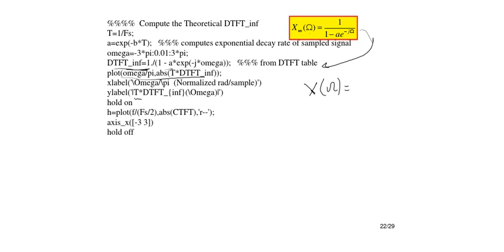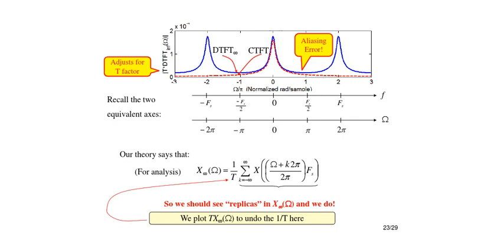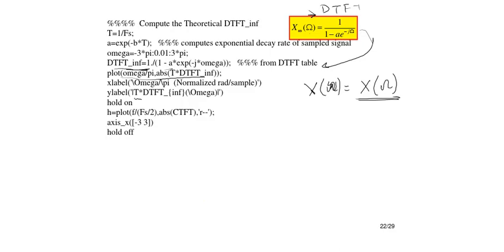So when we plot it, basically, I will show that. We are just plotting with respect to not omega, we are plotting with respect to omega divided by pi, right? Because DTFT is from minus pi to plus pi. So when we normalize it by pi, you get a normalized frequency that is from -1 to +1, and that is a normalized radian per sample.